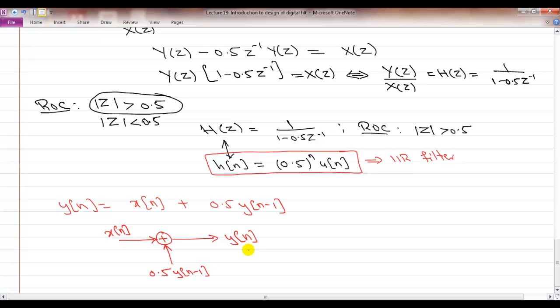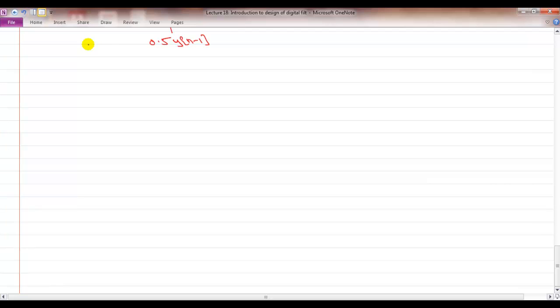So that is the other approach that you take if you want to approximate a filter that you want to implement in hardware. Okay? An IIR filter, but you must be able to represent it in terms of a constant coefficient difference equation. So the question is, is there a simple way of seeing whether an IIR filter has a form that can be written in terms of a constant coefficient difference equation? And the answer once again lies in terms of the Z transform. So you have to recall all the Z transform properties that you saw in linear systems, because they are going to be used heavily in this discussion.